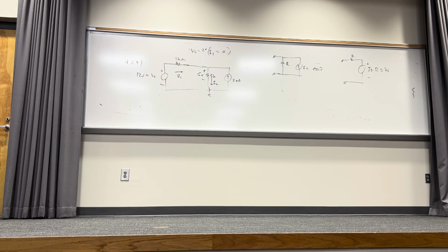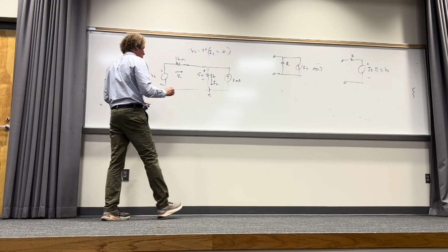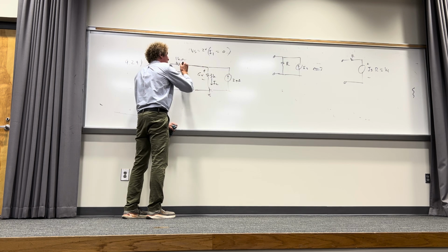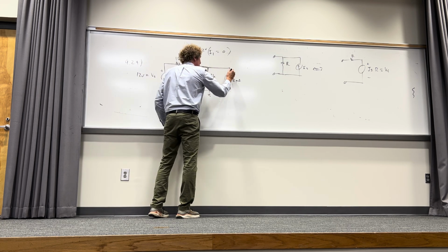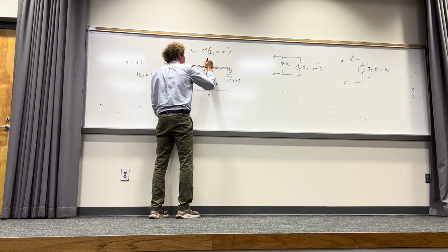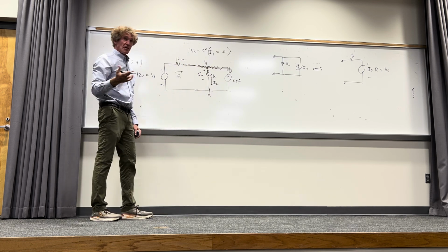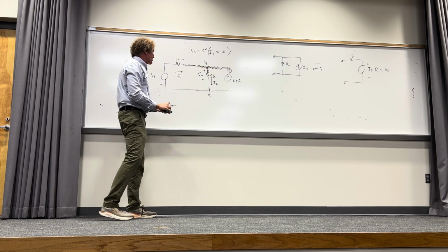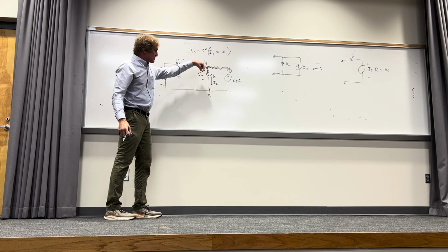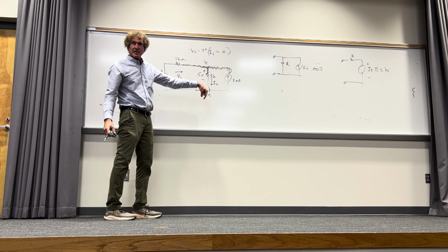Look, to save time and pain, I'm not going to go through every possibility, but I see a pretty easy way. We got a node here. There's got to be a voltage on this node. You all see it? I'm trying to make it absolutely clear. That diode's on, right? We'll call that V1 right there. With me? Now we can do nodal analysis. I1 plus 2 milliamps equals I2. Do you agree with that?